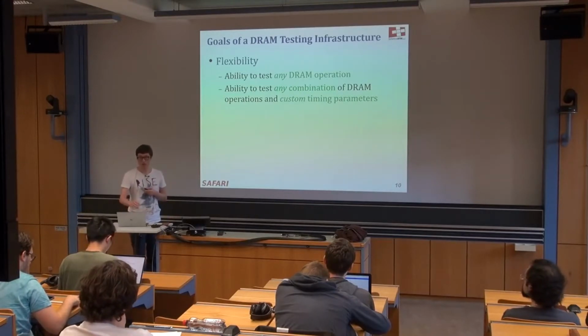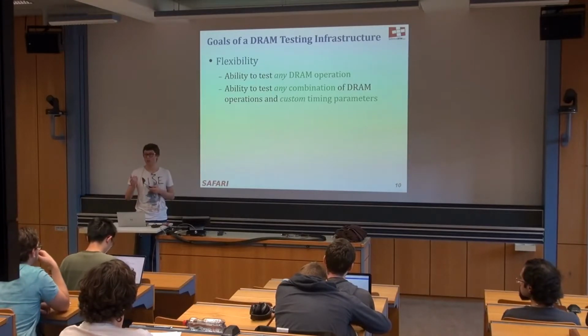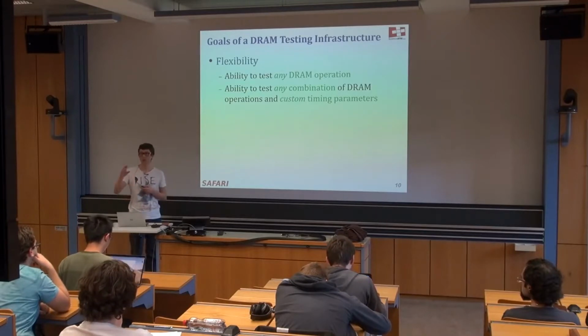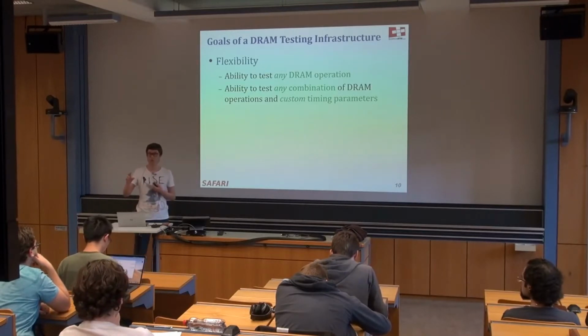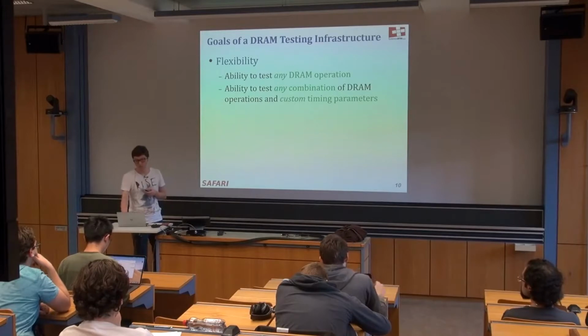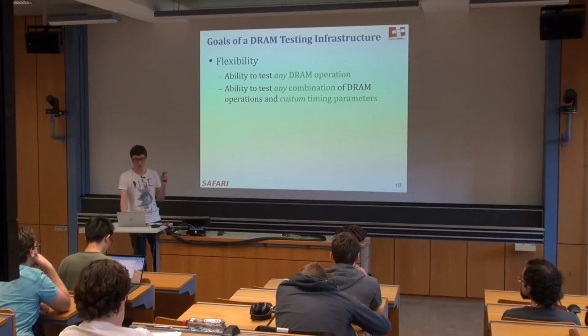Okay, and so here by any DRAM operation, I mean all the commands that a DRAM specification supports. If you open a DRAM datasheet, you will see a truth table with the commands supported. Some of them, as I mentioned, are activate, precharge, read, write, refresh.